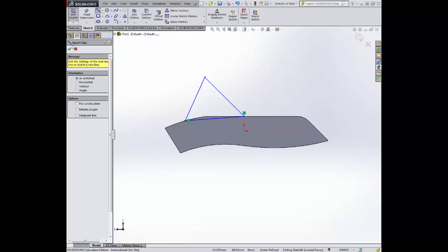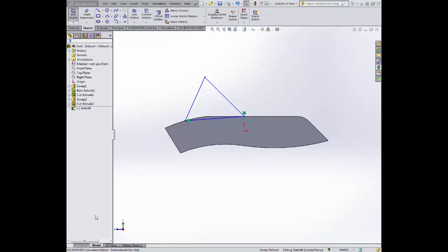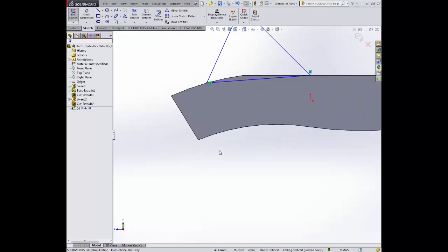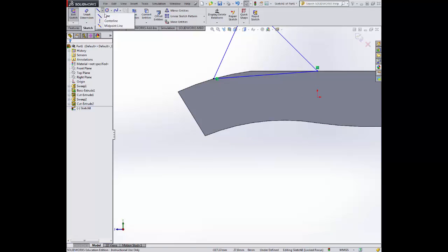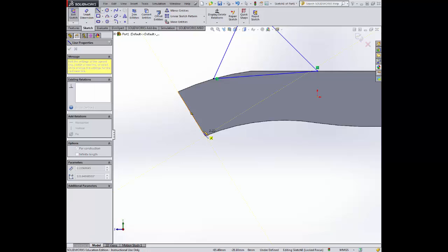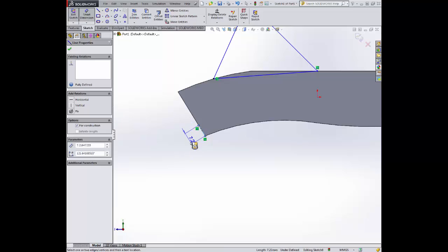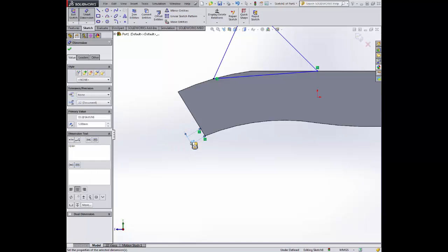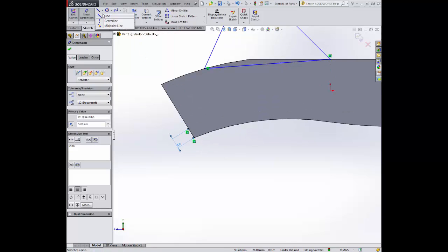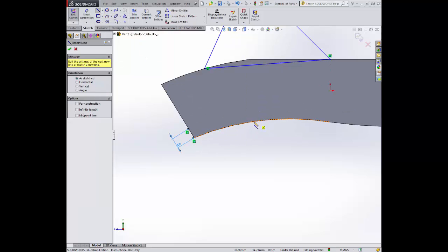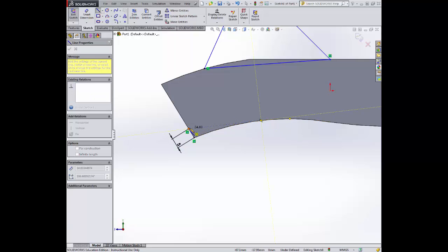Now you'll notice that when I selected the curve at the top of the knife, I actually picked the midpoint. And I'll do that quite a few times throughout this process because it helps you to understand your reference geometry. I'm drawing a line across the front of the shape, and I'm making sure that this particular measurement goes at 90 degrees to it, and it's 5 mil. And again, I'm looking for that center point. This one's a bit harder to find. So I'm going to use that one, and I'm going to click to the top of the line there.